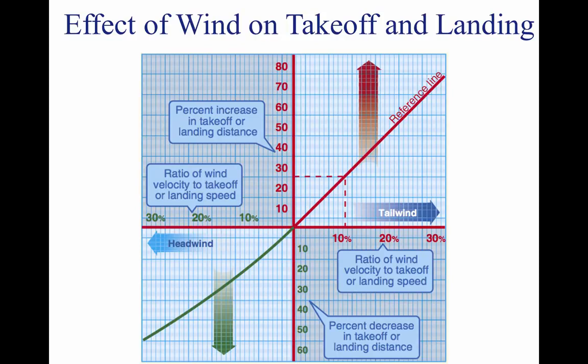In addition to the important factors of proper procedures, many other variables affect the takeoff performance of an aircraft. Any item that alters the takeoff speed or acceleration rate during the takeoff roll will affect the takeoff distance. For example, the effect of gross weight on takeoff distance is significant, and proper consideration of this item must be made in predicting the aircraft's takeoff distance. If the gross weight increases, a greater speed is necessary to produce the greater lift necessary to get the aircraft airborne at the takeoff lift coefficient.